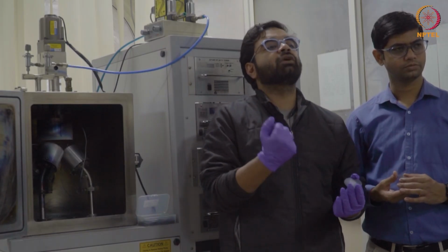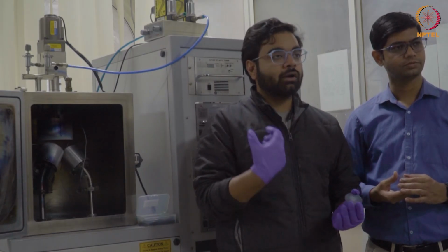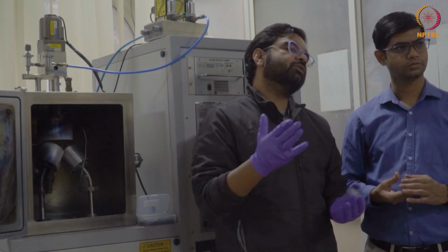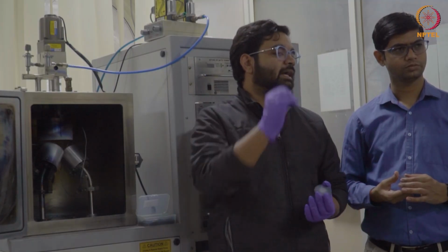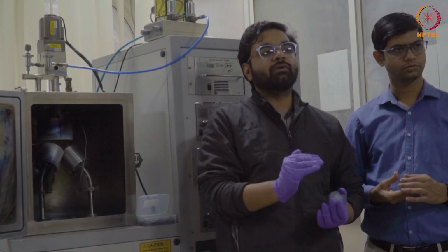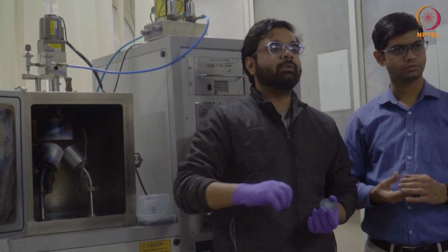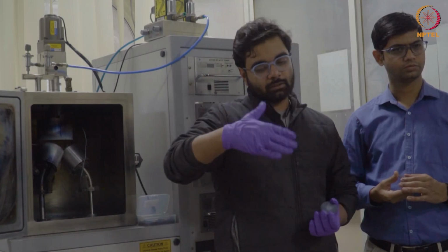It won't allow the gas pressure to form, and it won't allow the material to eject out. We have also observed while experimenting that at times PDMS also comes out from the surface, and some white layer is formed along the transferred material. Why does that happen? It happens because of the excess PDMS thickness. So we have to optimize that thickness.